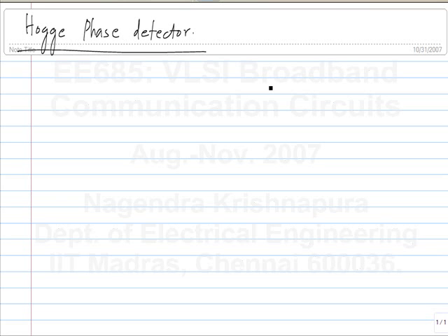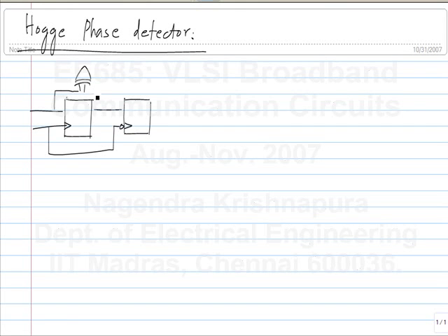So this consists of, the idea is to realign the data with the clock and detect the phase difference between the original data and the retimed data. Also, you would like the phase detector output to be 0 when the clock is in the middle of data.